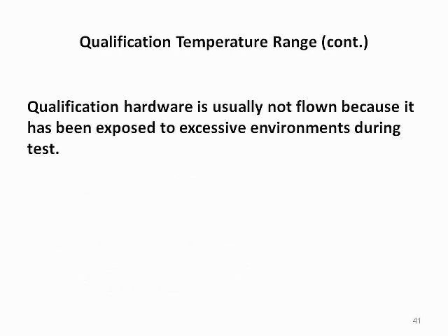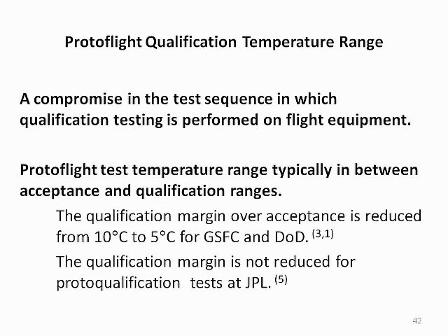One important concept to be understood here is that qualification hardware is usually not flown because it has been exposed to excessive environmental stress during testing. Building and testing qualification hardware that will never be flown is expensive. Proto-Flight qualification testing offers a compromise in the test sequence in which qualification testing is performed on flight equipment.